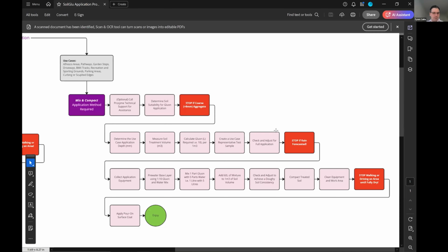Well, if you hit a sample off and it turned into a puck, you could put that in a tub of water and leave it there for a week, pull it out, and it's still a puck. It's not going to go soft again. So that's what I meant by irreversibly sets. Except it has that vulnerability between when you've applied it and setting: you don't want it to get washed out or oversaturated by some sort of water.